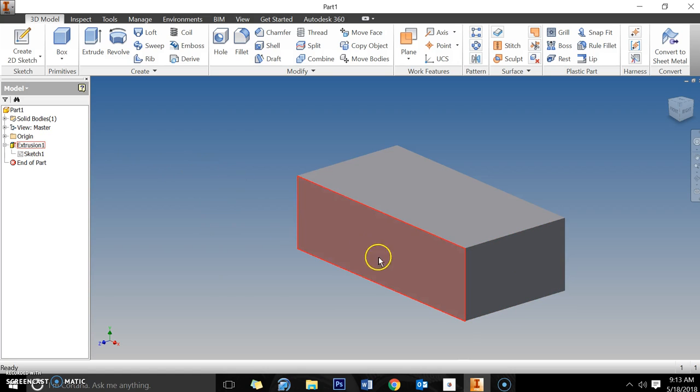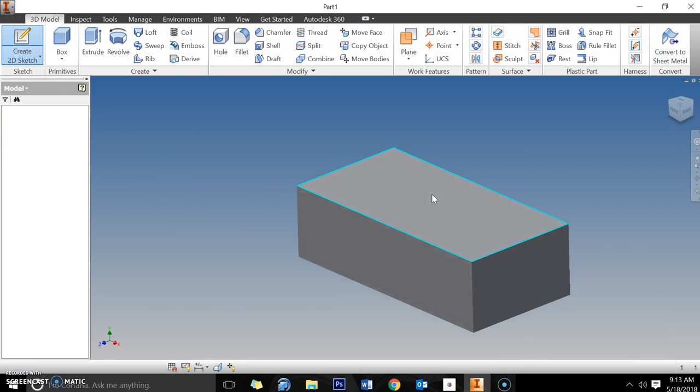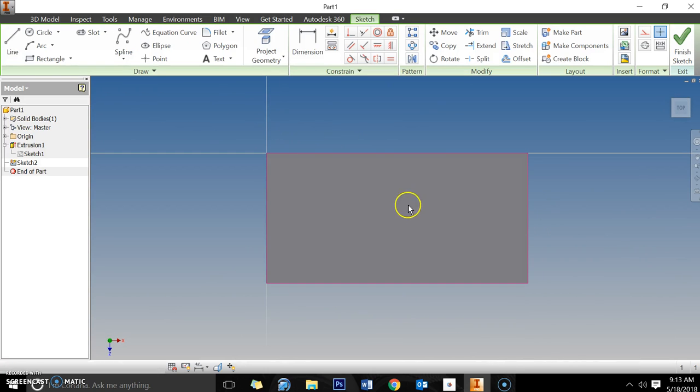All right, I'm going to go ahead and put a new sketch on the top surface, and that new sketch is going to be for the pins. So you see we have 8 pins on top of the Lego, and I'm going to click on the circle tool, and I'm just going to left click and drag out a circle that is 3/16. Alright, so I have a circle that is going to be 3/16 in diameter.